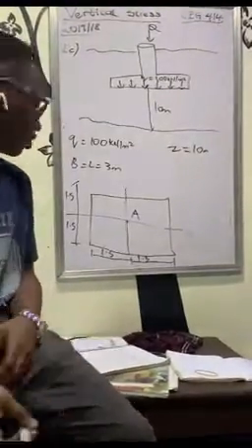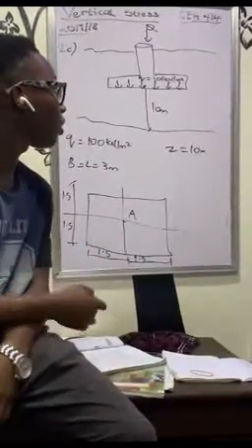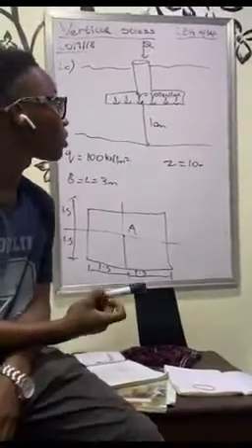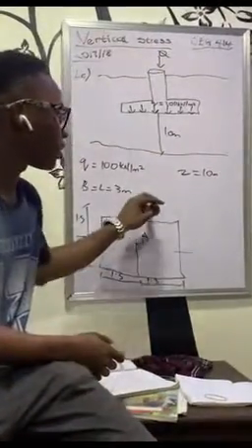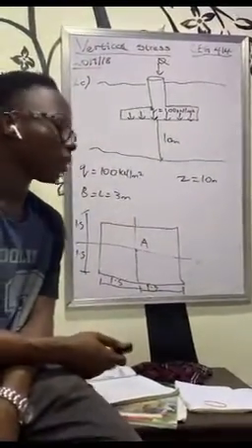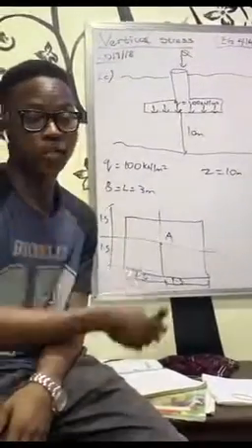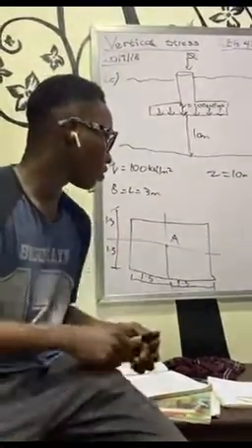So earlier we took a question where we had 2-point loads acting on the soil. We're given the depth at which we had to calculate vertical stress, and we're also given the radial distance r between the two forces and the point we're calculating vertical stress to. I explained that the total vertical stress is the summation of the vertical stress for each force.